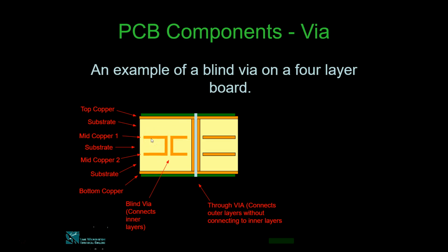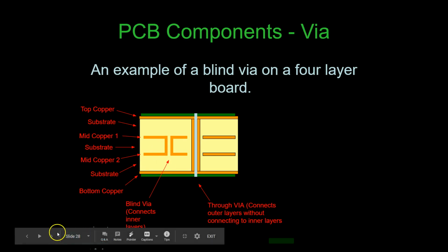And in this particular example, the through via is also mentioned. So here you see a through via is also mentioned. This green portion is your solder mask. Solder mask is here, and then this is the copper strip, copper layer, and this is a through hole, through via, and this is the blind via in a 4-layer board.